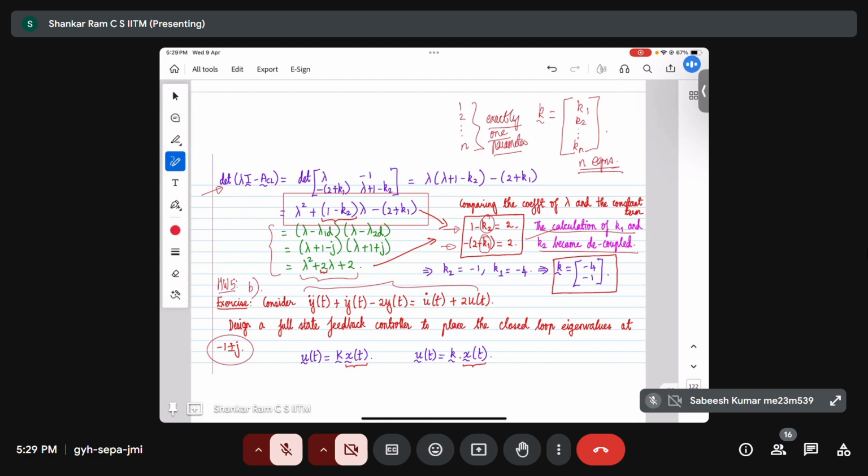Now, the biggest challenge here is that if I'm a practitioner, let's say an automotive engineer, and I use full state feedback for some application, I want to implement it on a real vehicle or a real system. The question is, I require knowledge of the state variables X. Who gives me that information? Because we know that u(t), the control input, is K times x(t). K, you and I will find through this design process. But then the question is, who gives us X?